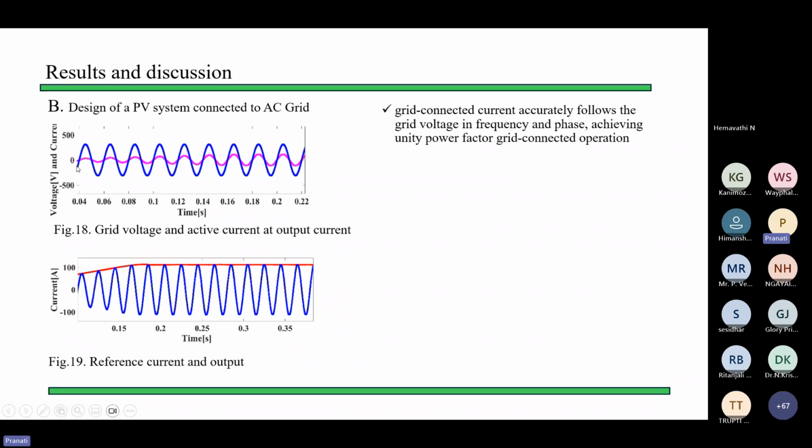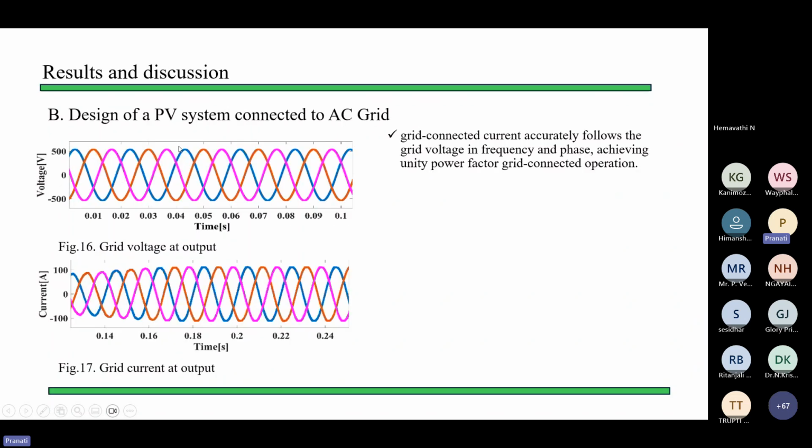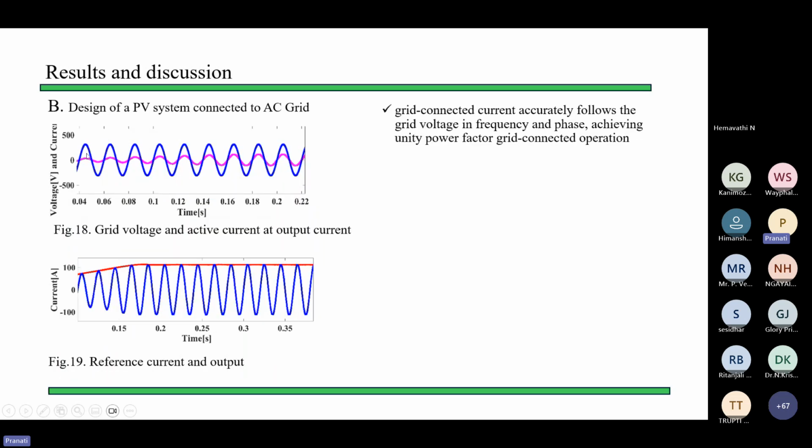See, you can see from this figure, this is our voltage curve in a single phase. This is our three-phase curve. This is our three-phase curve of current, and this is for the voltage. We have taken it through one demux and found out the single phase voltage and per phase current. This is VA and this we can say as IA, or let it be in any phase. See, the phase difference between this voltage and current is zero, which says that it is operated at unity power factor operation. That is, voltage is synchronized with the phase.